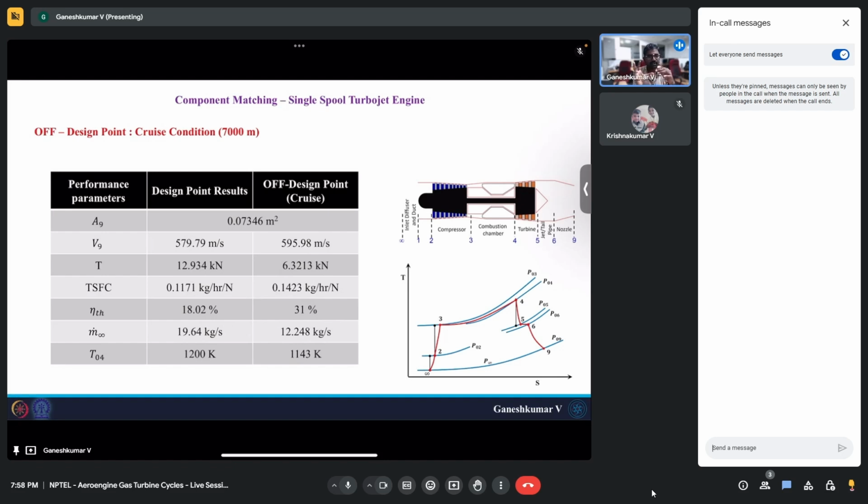You have to know that the engine is given, and for the compressor and turbine you know the operating maps, so you know the operating conditions, the operating characteristics. For example, the compressor can operate in these ranges of pressure ratio, in these ranges of corrected mass flow rate. These are the efficiencies that you have, and the speeds at which it can run. So that is the compressor map that is given. Similarly, the turbine map is given.